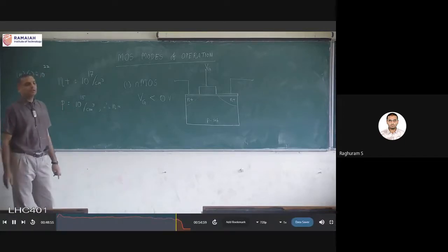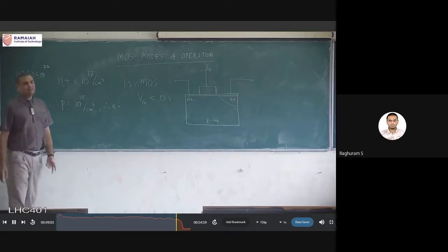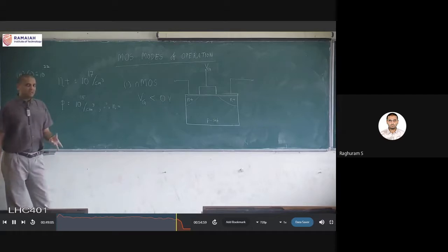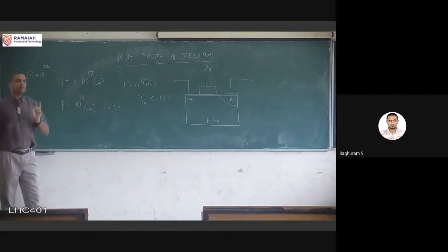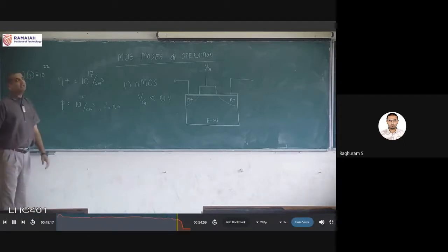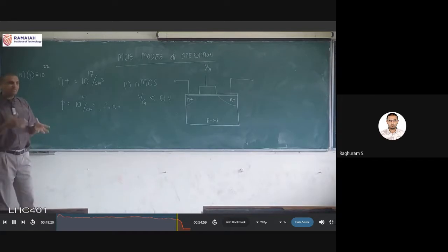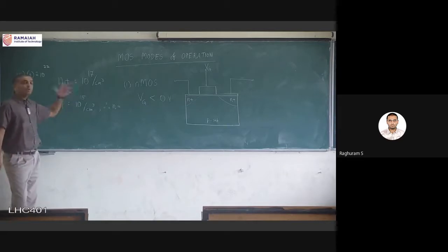you will not remember because that subject was removed. But if you look at the physics behind all these, one very important equation is there, which tells us that in silicon, under room temperature, the product is a constant. And what is the value of that constant? It is approximately 10 power 22. That is the concentration of electrons times the concentration of holes. If you multiply them together, you will always have the same value, which is 10 power 22.